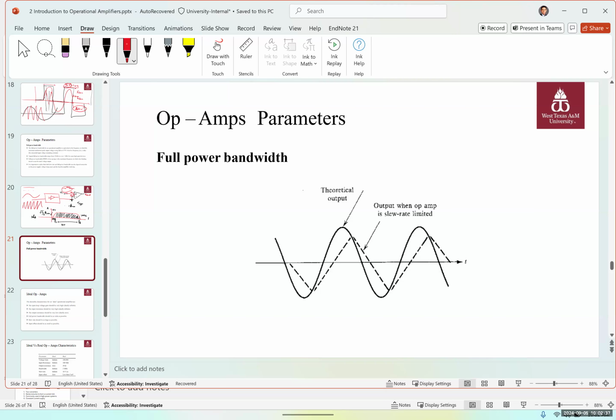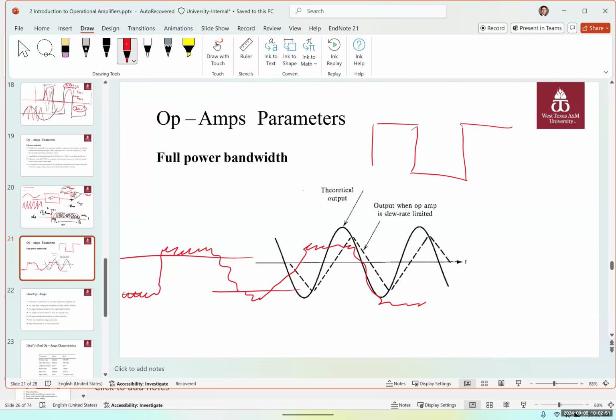And one thing that I wanted to add to that is that in a digital system, you never have a square signal, okay? What you're going to have is something like this. As long as this reaches that threshold in a digital system, it's acceptable. This is accepted as 1, 0, 1, 0, something like that. So sometimes it's distorted, but you still get the information out of it. And that's a great point. Yes, it doesn't need to be a clean square signal. It could be something that looks like this.